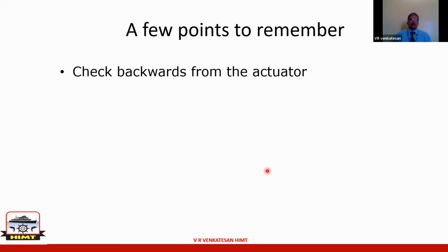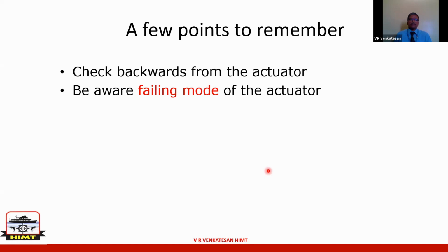Simple example is jacket water is rising. Then instead of fiddling with the controller, you should go straight to the 3-way valve. What should you note now? Jacket water temperature is going on rising. So what should you see in the 3-way valve? Anyone answer? With the rising water temperature, where should the 3-way valve be? Towards cooler. Yeah, bypass should be closed and cooler side should be fully open. If it is already there, then the controller has done its job.